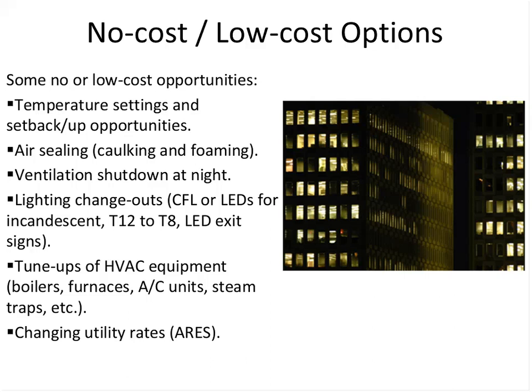And we used to think commercial buildings were fairly tight. Turns out they're probably no better than a lot of residential buildings. A lot of construction has not been that great, so there are opportunities to seal up commercial buildings as well as residential buildings. Ventilation. Ventilation is a human requirement in commercial buildings. If there's nobody there at night, there's no need to ventilate that building, so make sure that ventilation is shut down at night. If not, think about what can be done to shut it down at night.